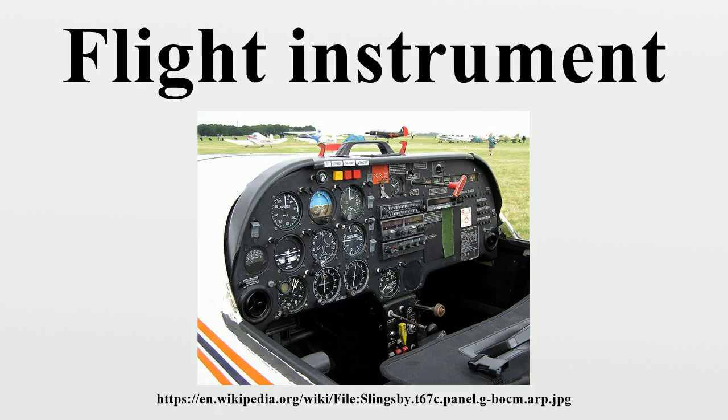The altimeter displays the altitude in feet, but must be corrected to local air pressure at the landing airport. The altimeter may be adjusted to show an altitude of 0 feet on the runway, but far more common is to adjust the altimeter to show the actual altitude when the aircraft has landed. In the latter case, pilots must keep the runway elevation in mind. However, a radio altimeter has been standard for decades. This instrument is, however, not among the Big Five, but must still be considered as a flight instrument.